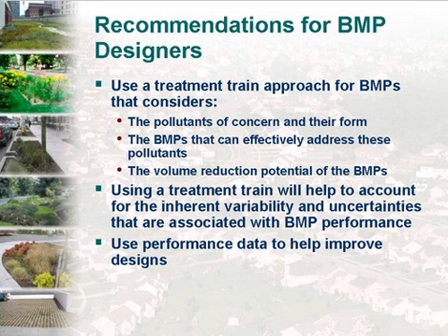And interestingly, with nearly 2 hours of discussion, we haven't talked much today about non-structural BMPs. Those would be things like pesticide controls and assuring that wide buffer zones are used next to streams. Those measures, in combination with the kinds of structural BMPs that we've been discussing today, would be the recommended approach. And of course, in terms of structural BMPs, you would start at an individual lot level and gradually move your way up to larger regional facilities, such that the pollutants literally have to be worn out before they can leave the site and enter the receiving water.